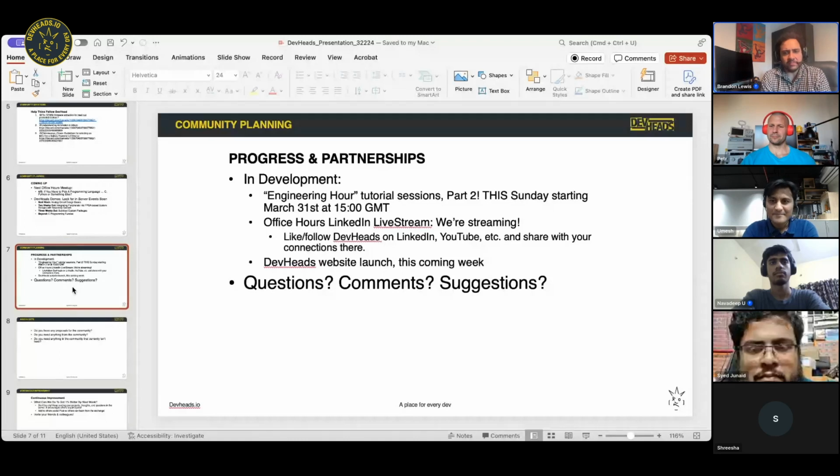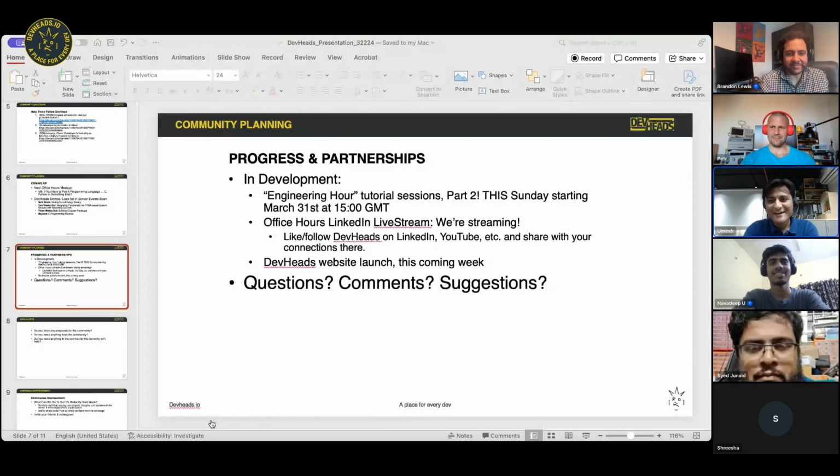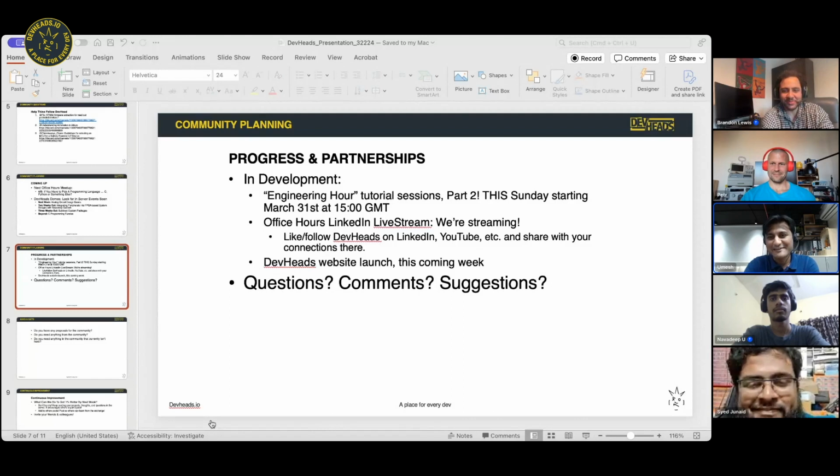Yeah, so before that, I want to add one funny part, because last engineering hours, you have seen I was in my office and I couldn't find a through-hole resistor of 1K because in my entire working, I just use SMD components for production. All the through-hole components are in my home lab. So this happens right now with everyone. And for an LED protection, you practically just need 125 ohm or something, whereas we always, out of habit, put a 1 kilo ohm resistor because that's very easily found in through-hole. So just wanted to share.